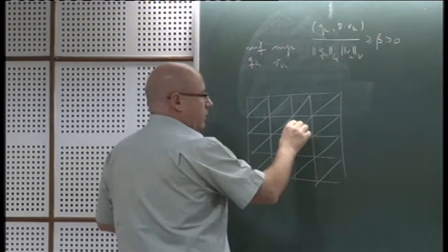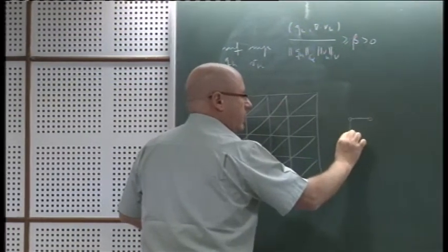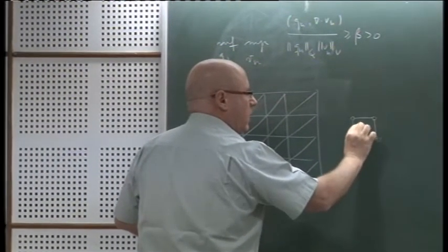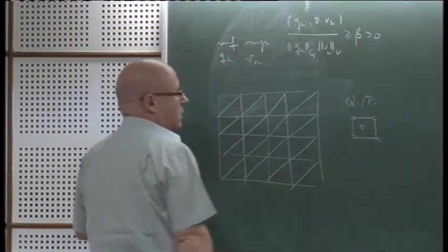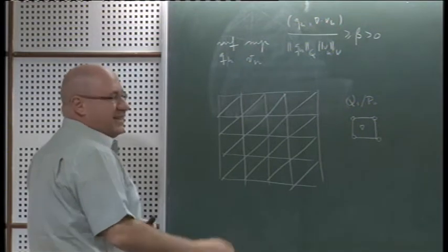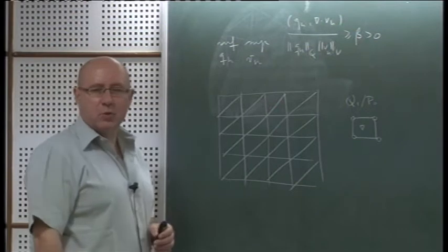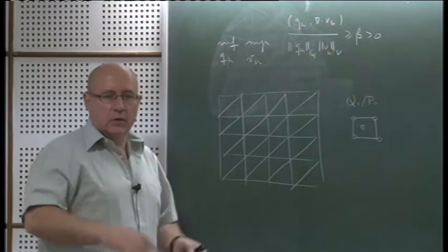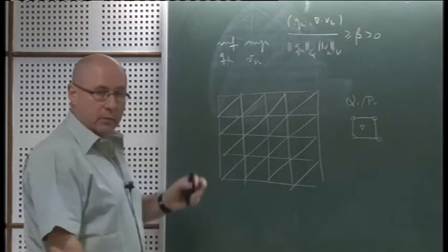You know that if we discretize it in quads, we would use elements of this type, using Q1, P0. So Q1, P0 would be this. Okay? And that element is, you know, in the border. For regular meshes, it doesn't work. In other cases, it does work. In fact, it gives very good results when it works. I like that element very much.